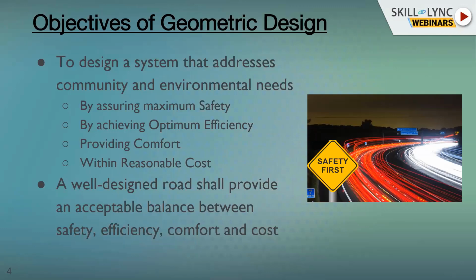At all these layers, there are alternate materials you can use. When you use materials from nearby places, you can certainly reduce the cost. Even using available government land, making the road pass through barren land instead of agricultural land if possible, are all cost cuttings you can do.